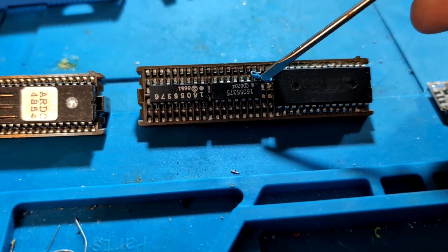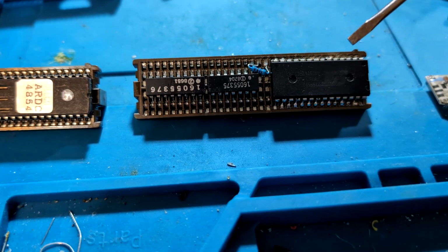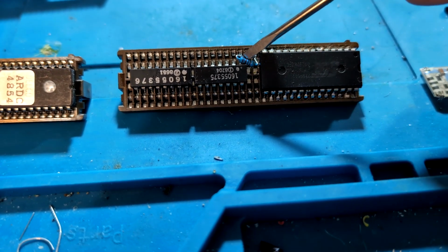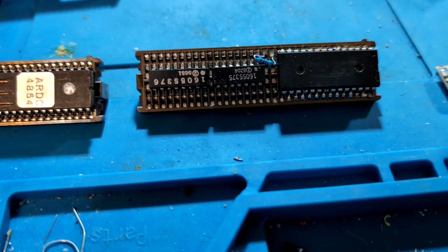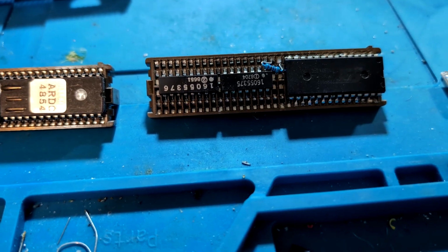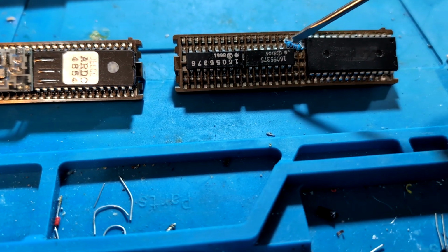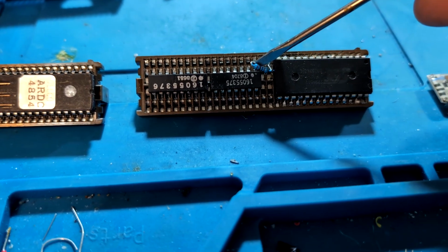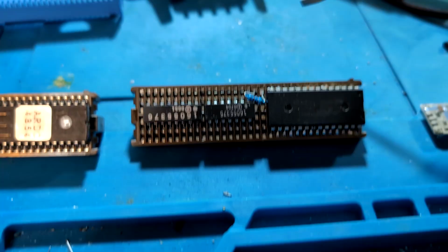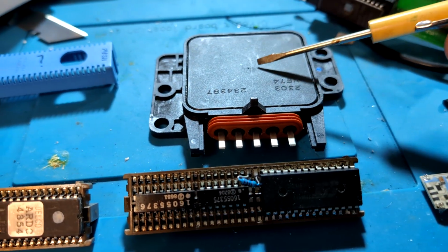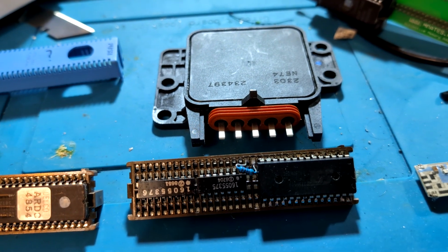Do that, and the computer will now see that 100 k ohm knock sensor as a 4 k ohm knock sensor, and now you don't have the check engine light being set, and it still works correctly. So that's what this resistor is for. That's one thing that you will need to do if you're going to maintain the use of the original knock filter.